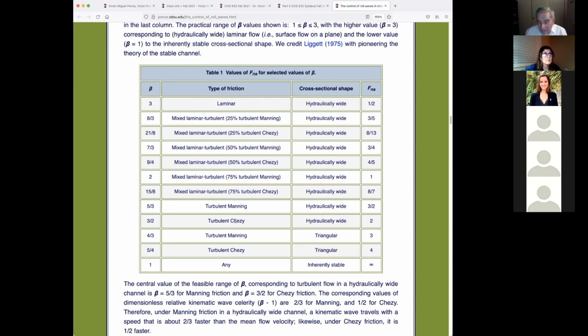And they have a tendency not to use Chezy. What they're saying is, well, Chezy was varying with the stage while Manning doesn't vary. That's not correct. All these values vary with the stage. That's obvious. But, be it as it may, that's the history of what actually happened in terms of the recognition of these two gentlemen. Chezy is theory, Manning is practice. Chezy is correct, Manning is incorrect. Yet Manning is used by 99% of the engineers.